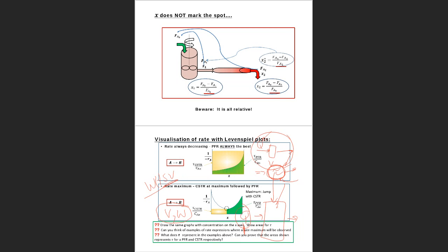Standard cubic feet per minute is a variable that measures a flow rate. So this is a unit that's got a specific volumetric flow rate in a sized reactor. So it's not like that at all. Residence time is for a specific reaction: how long does it take to complete? And therefore, if I start sizing my reactor, I need a starting point to say, okay, try a mass of this, just to get me started on my design journey. Okay, so thank you very much for that question.